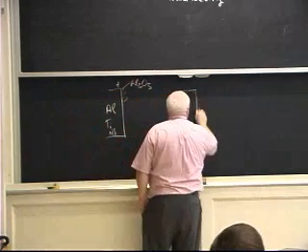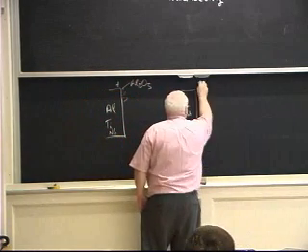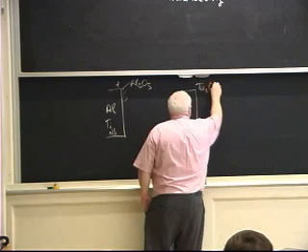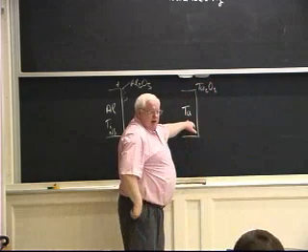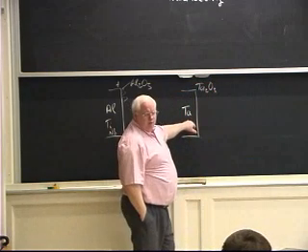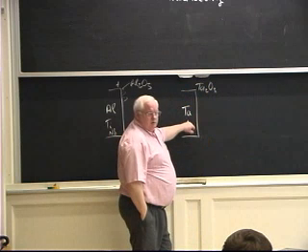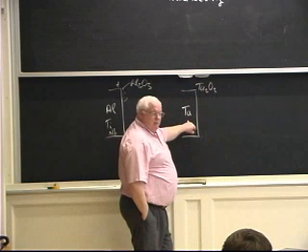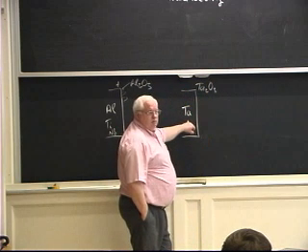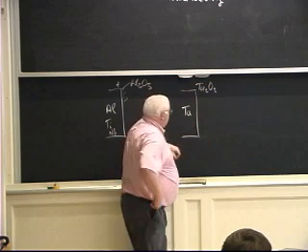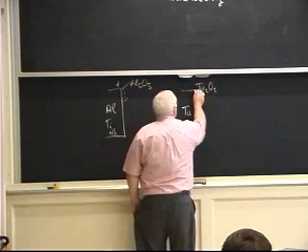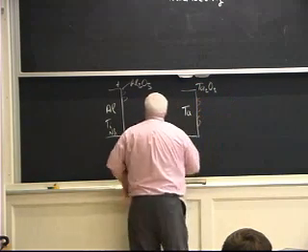For capacitors, let me back up. Let's say this is tantalum, Ta2O5. Most expensive tantalum, and I think I mentioned it before. It's one of the more expensive metals, about the price of silver. But it makes the best capacitors in the world. And the reason is you get a very high surface area when you grow the tantalum oxide.